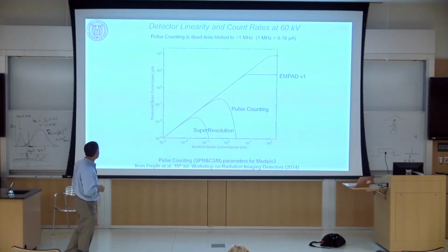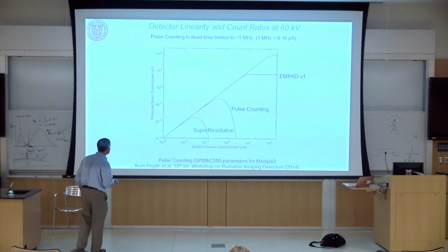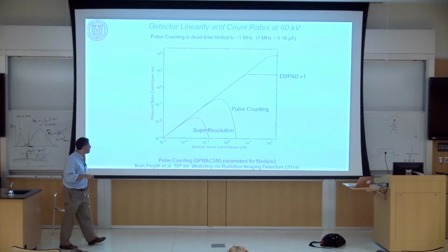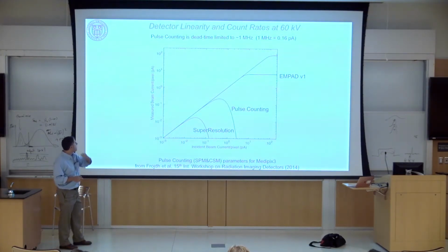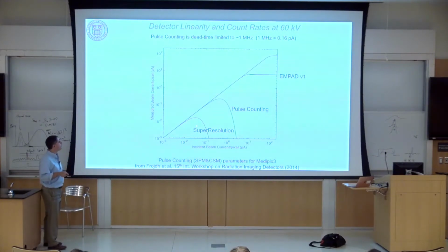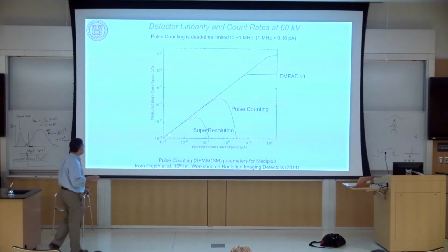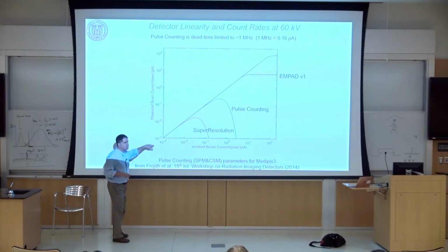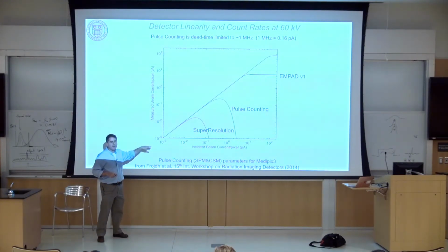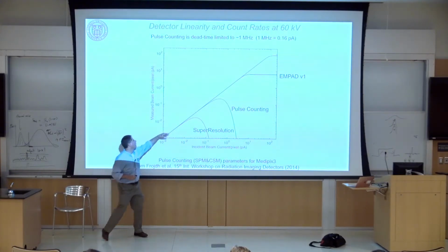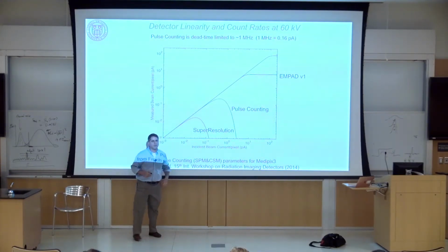And that's a very low number of counts. This is in picoamps per pixel, and this is in 1 millisecond. This would correspond to 1,000 electrons there, and you're safe up to about 100 electrons. The K2 is sort of down about here because it's 25 electrons, but it has so many pixels you can just add pixels next to each other, and then it brings it up and looks comparable to this thing again.